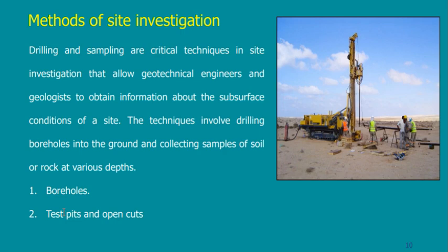So this and this may help me a little bit, especially that usually the very weak soil is on top. The deeper you go, the better the samples. So if I can check the first 3 meters, okay, it may help in some cases in roads, but of course it will not if I'm doing a building like the one that we are staying in here. No, I cannot do just test pits. I need boreholes.